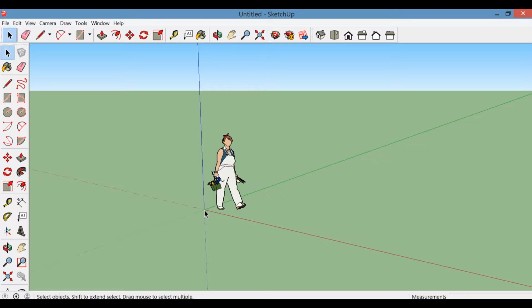To dimension lines, you'll want to click the start point of your line, and then immediately type in the dimensions of your line, and finally specify the unit. So let's say I've just specified the start point of my line. Then if I wanted to have a line of 1 meter in length, I'll type in 1 m. Or if I wanted it to be 1 centimeter, I'll type in 1 cm, 1 millimeter, I'll type in 1 mm, and so on. And you'll notice that your dimensions will be written into this white box on the bottom right corner. Once you've entered your dimensions, hit enter to finish the line.